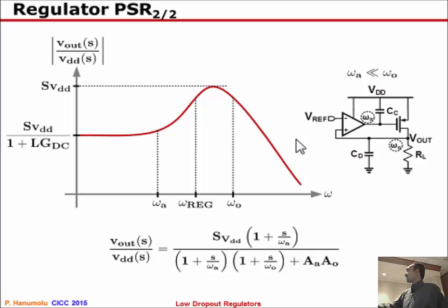Okay. So if this moves at 1 Hertz and if the loop bandwidth is at 1 megahertz, then V out will see only a very small fraction of VDD, and what that fraction really depends on is what the loop gain is. Now, if you keep increasing the supply noise frequency, you are going to move in this direction. This is frequency. This actually should be log omega.